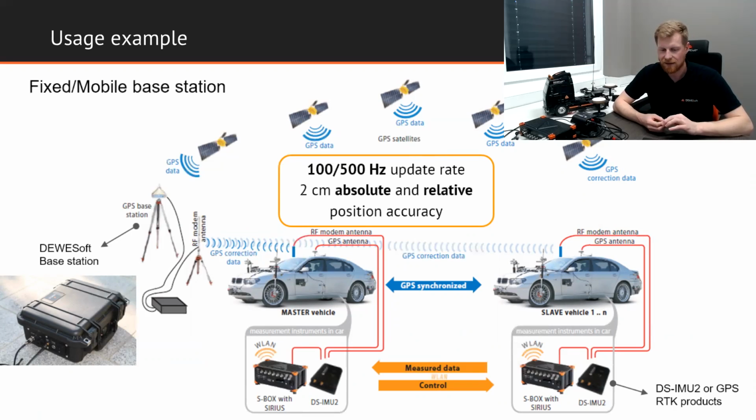So in the end, we get all the data in one vehicle, which is perfectly synchronized from both vehicles with high accuracy. Together with that, we always know the exact orientation of the vehicle, even when it is stationary. This is one benefit of using IMU devices compared to standard GPS devices, where we get the heading only when we start moving, from the information from the velocity. And we also get all the accelerations, roll, pitch, yaw, and so on from the device.